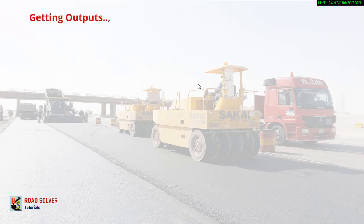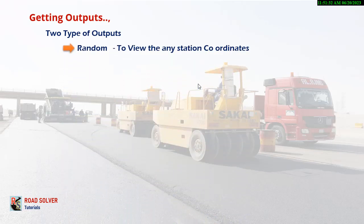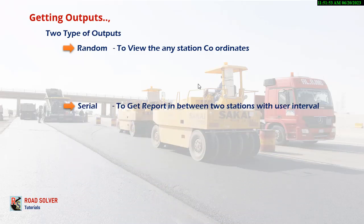Now what outputs can we get from Road Solver? There are 2 types of outputs. One is random. That means with the random station you can see the station coordinates. For any station between the beginning and end, you enter the station and press view, so you can get the coordinates of any offset, center or right or left, whatever the user requires. The second one is serial.